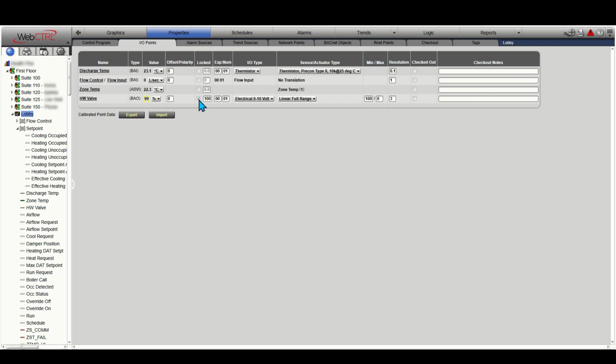Be aware that on larger databases, the initial Global Modify search, as well as the server sending the commands out, may take some time. Be mindful of any potential lag when using a Global Modify command. In doing global locks, for example, be sure to modify the value first to avoid any stale, undesirable lock values taking effect in between the two Global Modify commands.